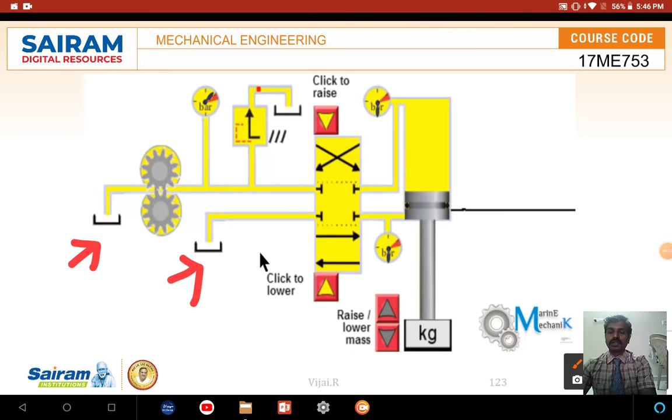Next is the pump, which is a gear pump symbol, shown as a simple mechanism, because for rotation we draw it like this. Here this is the pressure relief valve, and this is the solenoid operated or manually operated directional control valve. Four ways over there, ports 1, 2, 3 and 4.